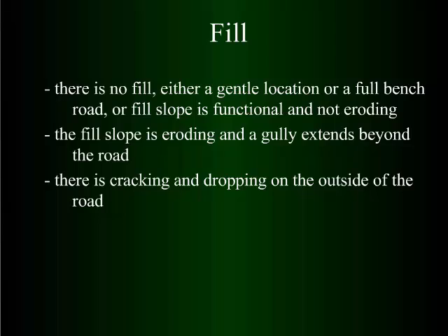If you can determine the reason that you have tension cracks, most times it's water. Your ditch on the inside may not be deep enough. It may not be functioning. And a lot of times it's the water being introduced that causes the tension cracks.